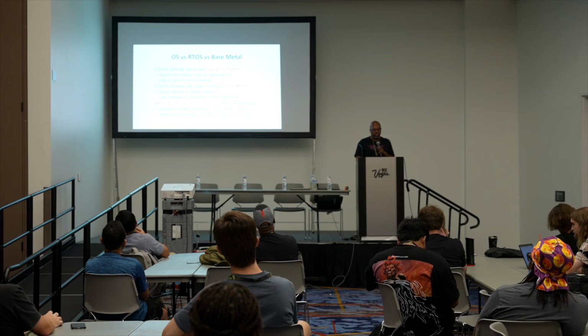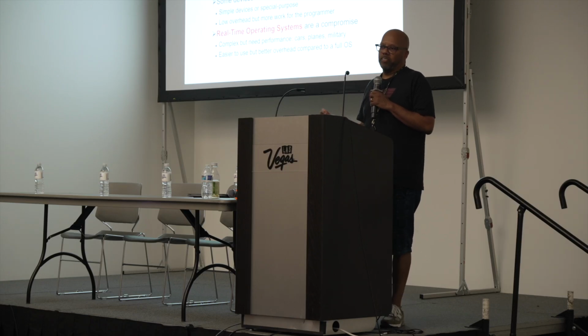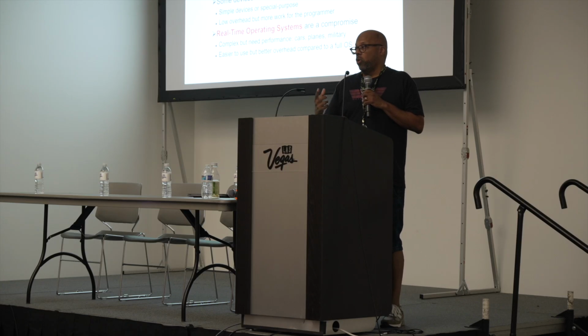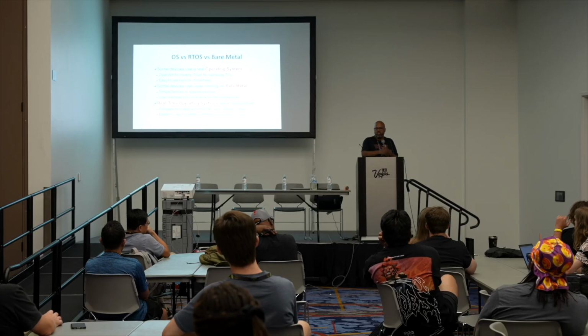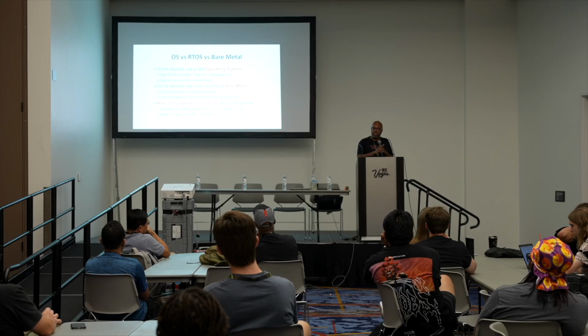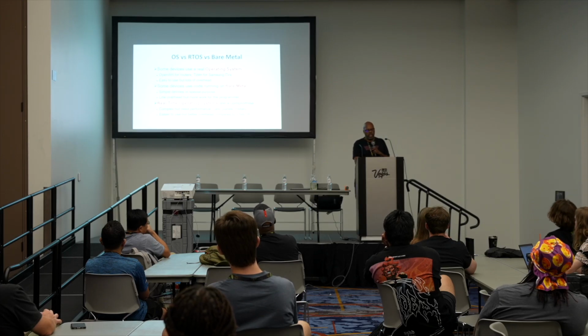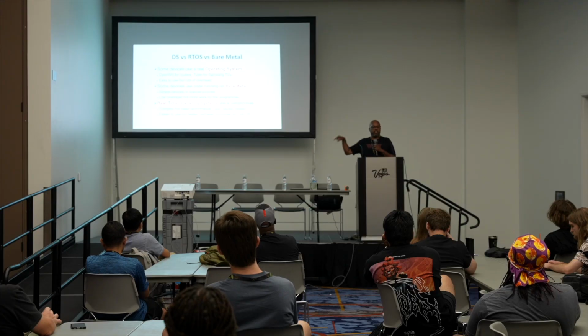Now the downside of that is that it's easy because it's running Linux, but there's overhead, right? You're running an operating system on top of the microcontroller. So the operating system is a burden on the microcontroller, meaning it requires a lot more memory and a lot more flash and all kinds of junk, right? So if you want to be really cheap, you might not want to use a full-on operating system. So then sometimes people use bare metal. That's the other way.